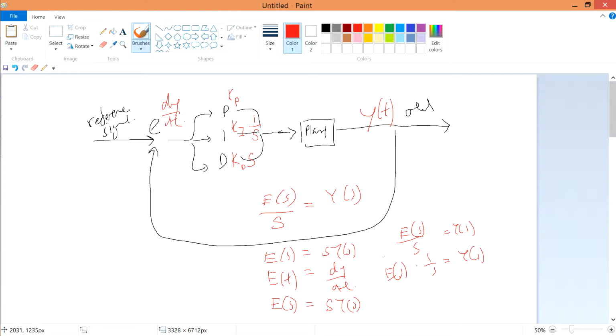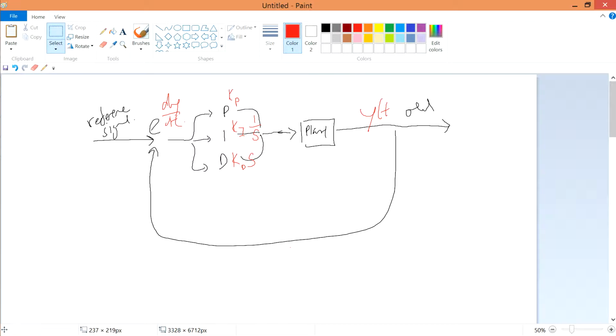So we know from this that your E(s) or e(t) equals dy/dt, which is here. Once you go through the 1 over s, you become integrated, and therefore it's over here. I hope that this is pretty clear and in-depth before we go on to other stuff. Since integration you're dealing with 1 over s, then differentiation is simply s. You can just remember, or you can just try it out. That's the same example. Just take note that integration is 1 over s and differentiation is times s.